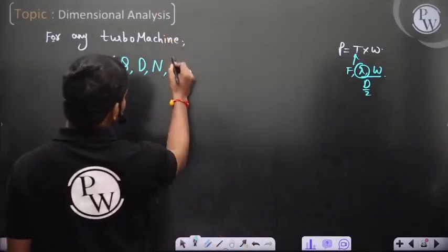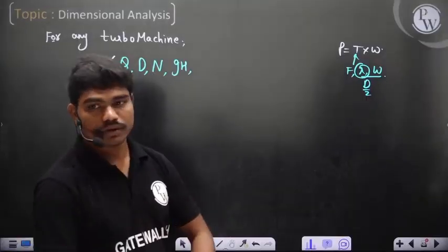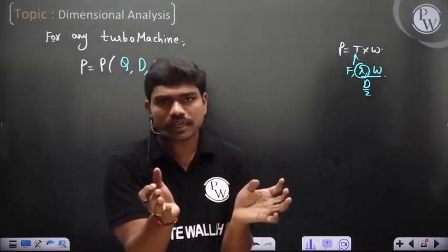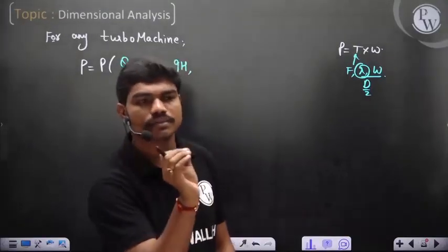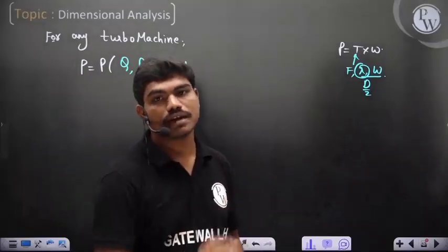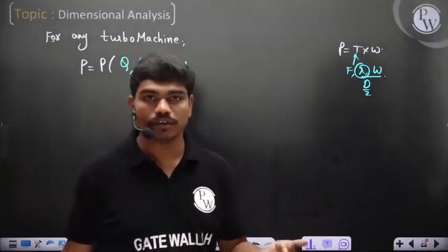Then head available, when the fluid is coming, at what head it is coming, means velocity basically. So if you see at what velocity it is coming, let's say I'm impacting 100 meter cube per second, but at only 1 meter per second, a very slow impact. There is a large fluid but very slowly it's going and impacting, then ultimately power will be low. But if there is a high fluid with high velocity, then power increases.